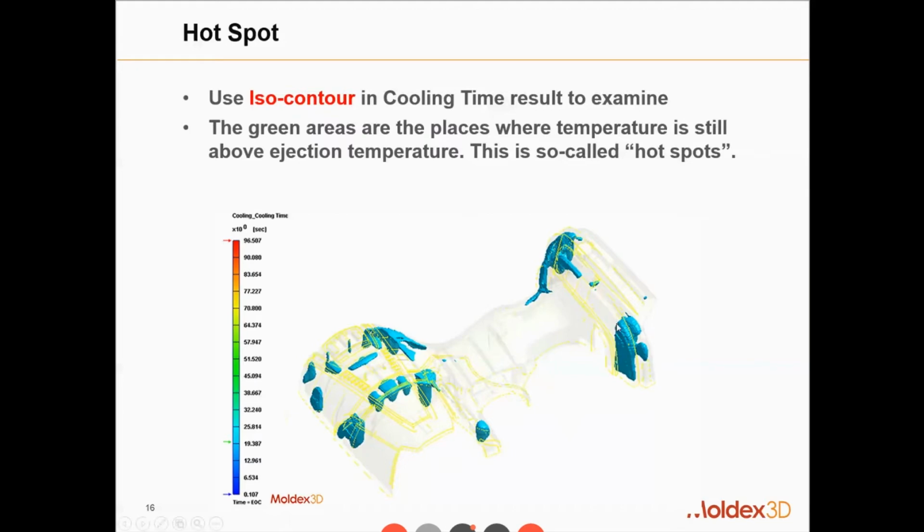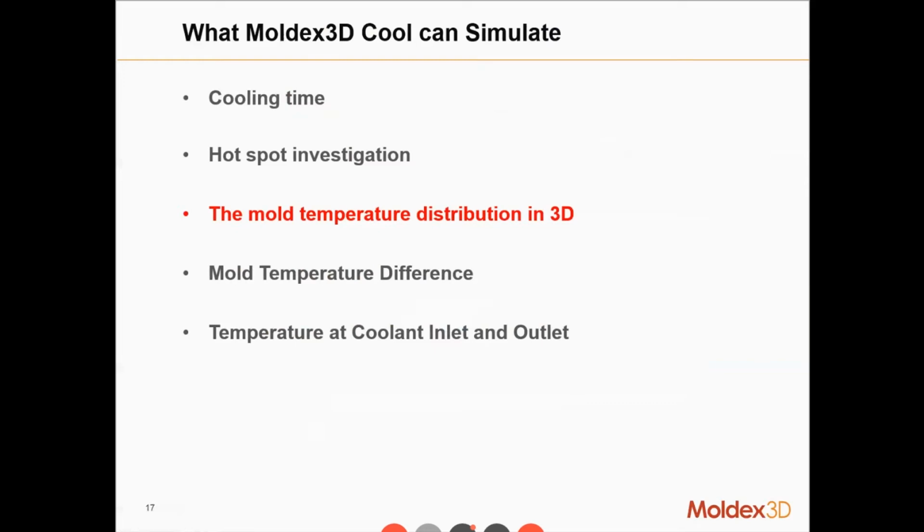You might want to avoid those regions, avoid setting an ejector pin at those regions. Okay.